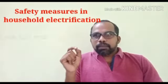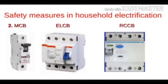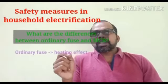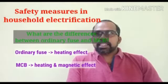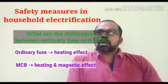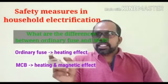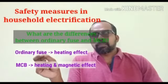The second one is MCB, ELCB or RCCB. Nowadays we are familiar with MCBs, ELCBs and RCCBs. So what are the differences between an ordinary fuse and an MCB? An ordinary fuse makes use of the heating effect of electricity, while an MCB works making use of the heating and magnetic effect of electricity. The current in the circuit may increase due to short circuit, overloading, excess flow of current or other problems in the insulation. The higher temperature makes the fuse wire melt and the flow of current stops. That is what happens in the fuse wire.